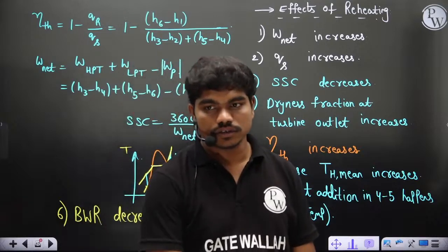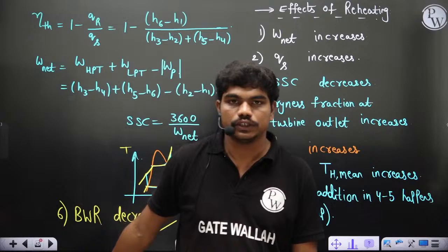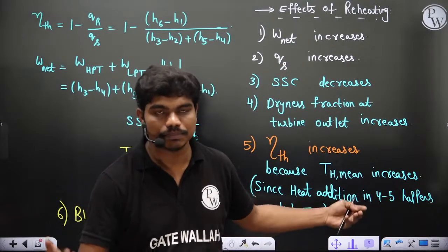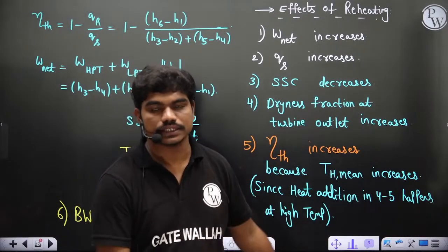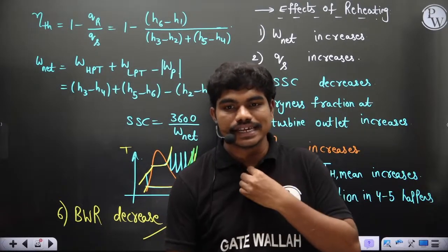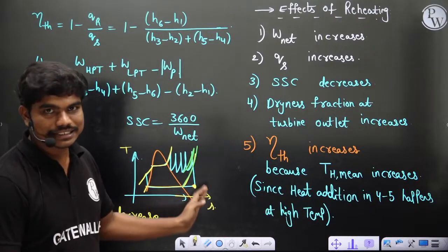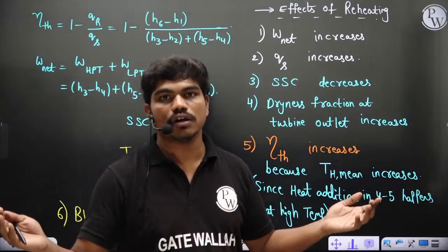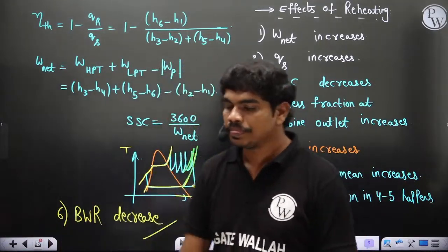Okay, clear? Decreases, as you know. Now you see all these points are very much easily understandable to you. Okay, nothing to mug up anything. Simple. Based on the knowledge of numerator and denominator in a fraction, you are able to decide all these things. Okay, so no need of remembering anything and all. You might have understood it. Why I'm not going for multiple reheats? Because as reheats increases, the pressure difference across the turbine keeps decreasing, and after some reheatings, it not at all matches the turbine cost and the excess power you are generating. Okay, so that's why we generally do only one reheating.